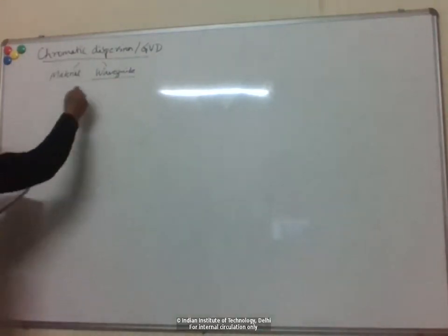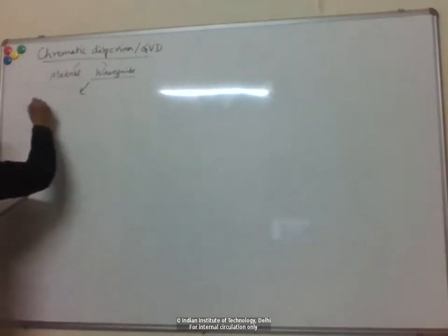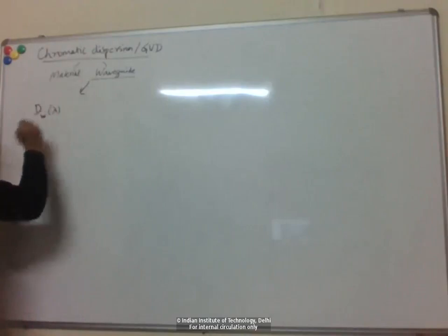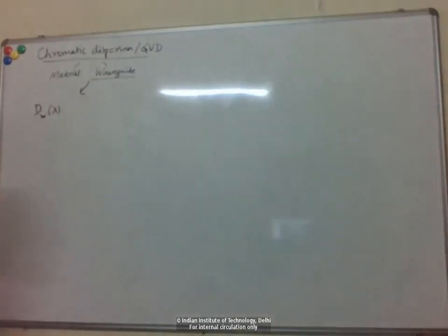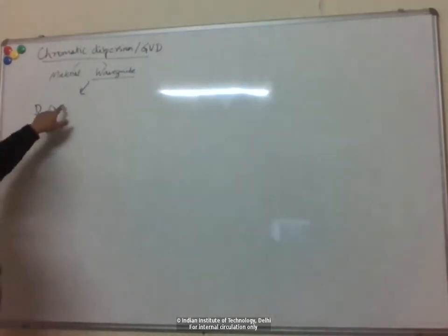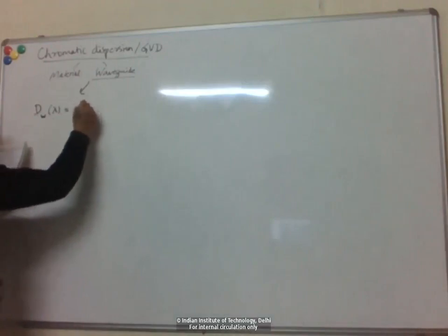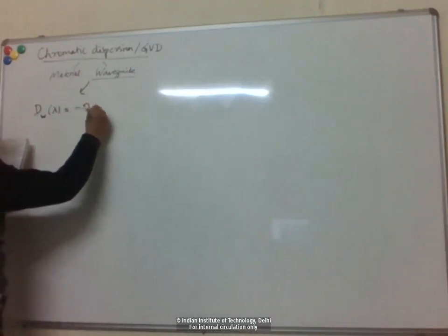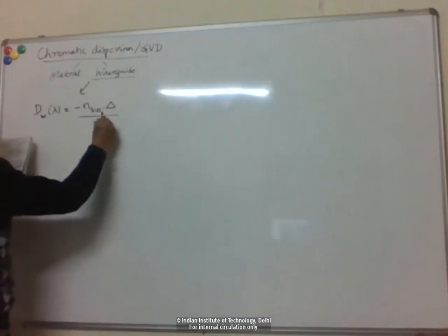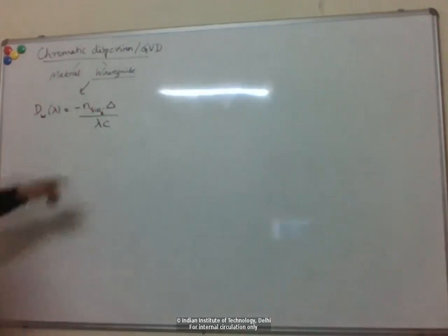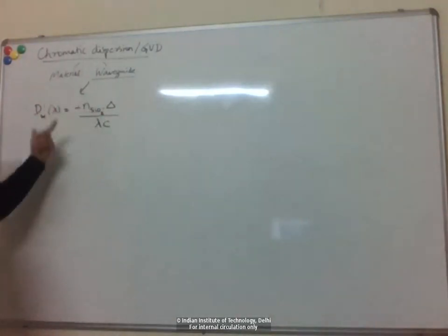So we had written down this expression for the waveguide dispersion, right? So this is the capital D parameter, the dispersion parameter that we introduced last time, right? So from the waveguide contribution, we saw again, we can write it like this. Okay, so last time we had two terms, right?